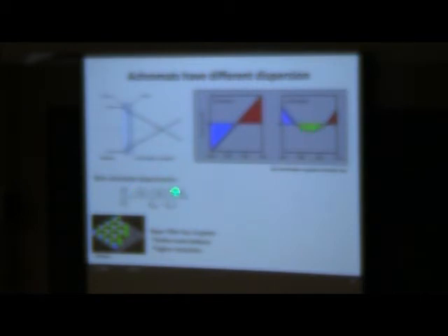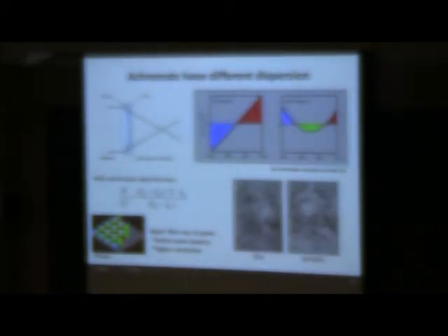So the average of red and blue, and then the green one, are the things that you subtract. And that's really nice because the Bayer filter has twice as many green pixels as it does red and blue. So when you add the red and blue, you come up to the same sort of noise levels as you get for the green already. So you're just taking advantage of what already exists.